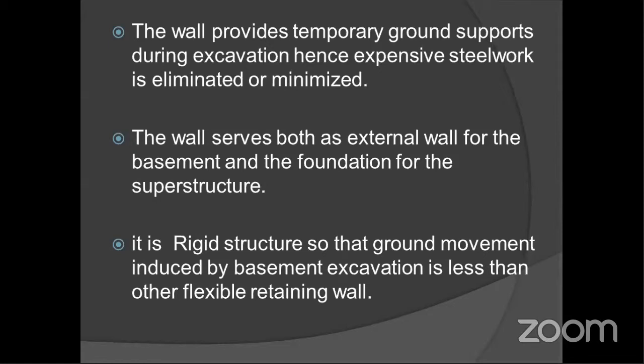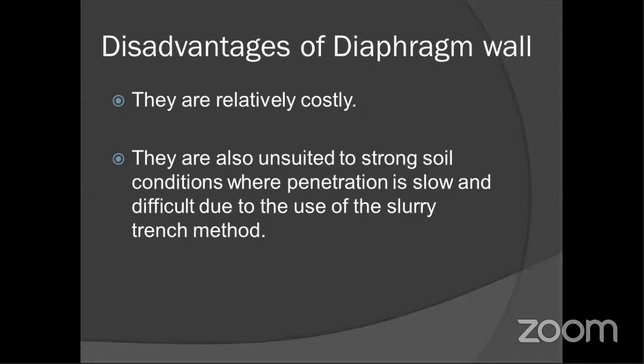And if you would like to talk about the disadvantages of the diaphragm wall, the main thing is that it is relatively costly compared to other methods, but it is fast. The second thing is that in some places, such as hilly areas, where hard rock is found at minimum depth only, it becomes difficult for us to go for this, because for all these grabbings we have to use big and massive machinery so that we can achieve that.